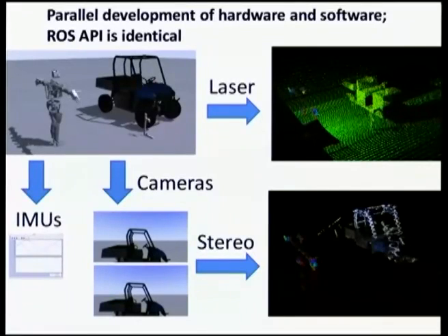So Gazebo, this open source simulation platform that many people at the Open Source Robotics Foundation are working on, can simulate all these different sensors. We have on the upper right the laser scanner coming out of the robot's head. We can simulate those collisions with the world. Then on the lower left there's a stack of 2 images. Those are the right and left cameras on the robot's head. It's a little hard to see at this resolution, but they're slightly offset horizontally.